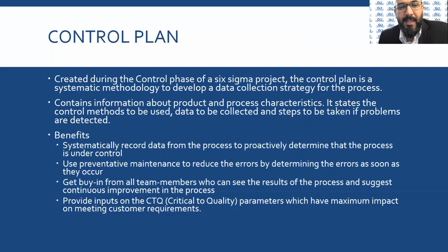Why is this important? Why should I create a control plan? There are a lot of benefits of developing a control plan. One is systematically recorded data from the process to proactively determine that the process is under control. So one is, as I mentioned here, we need to see if the process is in control or out of control, and we need this plan to follow some steps, and these steps will help us to decide if the process is in control or out of control.